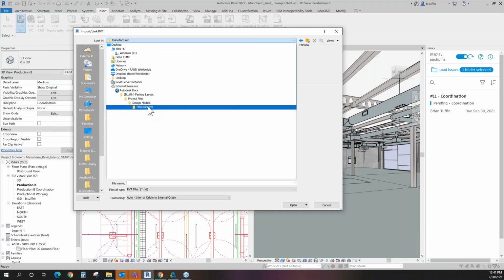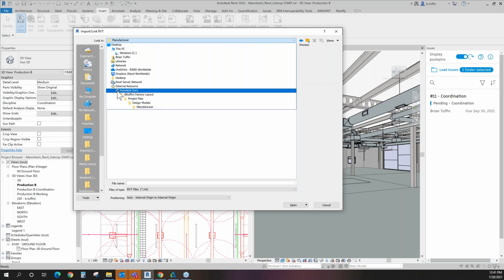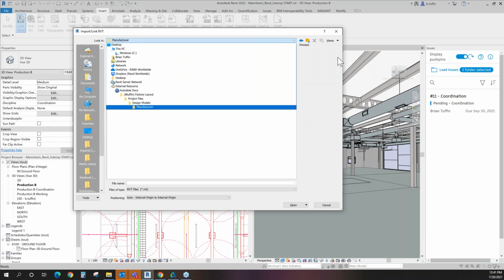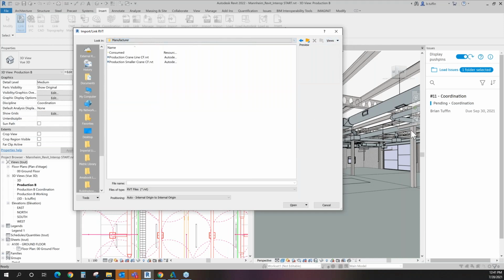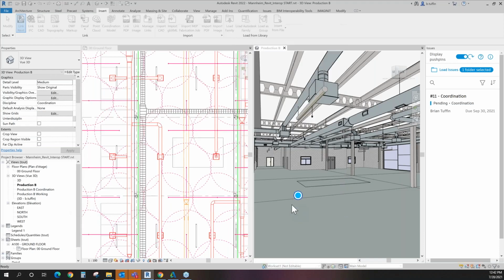Now, at this point in time, Autodesk is constantly updating the Desktop Connector. We're seeing updates happen every 1 to 2 weeks, gaining us greater functionality. If I choose to connect it or link it in through Docs, when I go to publish my Revit file, I will not see that link. That's why I chose in this case to go ahead and do the central file so that we can show that link a little bit deeper.